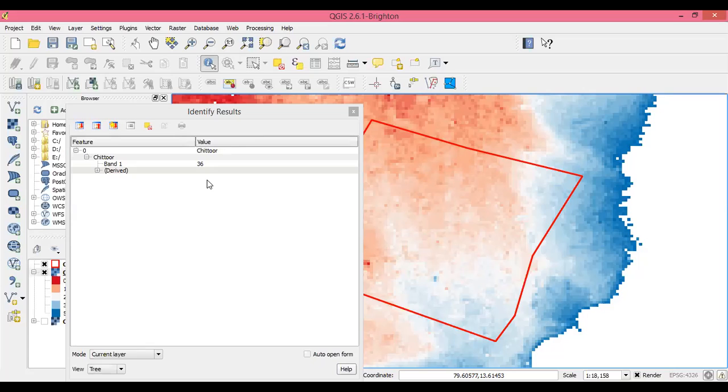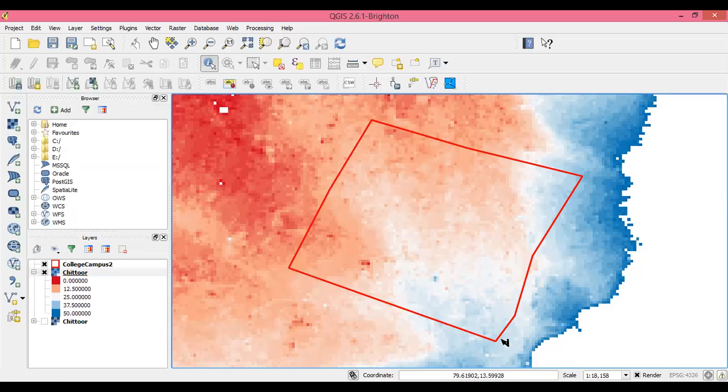The maximum length of travel, here again, if you had to do it very accurately, you would have to find out exactly what path the water is going to take to reach the outlet of the watershed. Here again, I would just suggest that you take the maximum distance that you can, the maximum distance in the entire watershed. You can do that multiple ways. This distance is one maximum, this is another maximum. You take the average of that.